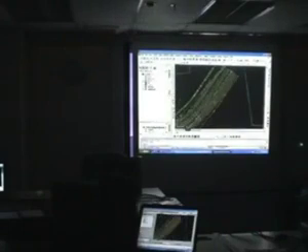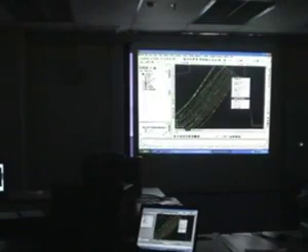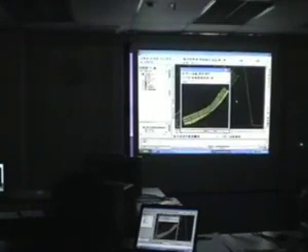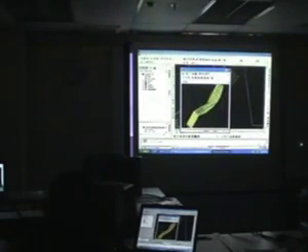So let's zoom in now. This is the corridor that has been created for this project. I'm just going to select the corridor and look at the object viewer. Hope it works. The object viewer basically is for you to view the object. They've got all these zooms and the shade and the orbit. This is an advantage in the sense that with AutoCAD you also have all the orbits and everything, but you orbit and you view everything in the drawing. With the object viewer, you can just select one object and say, I want to see what this looks like. So it's a lot easier to check what has been done.